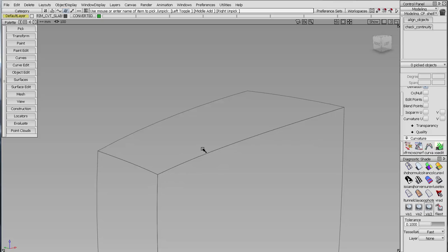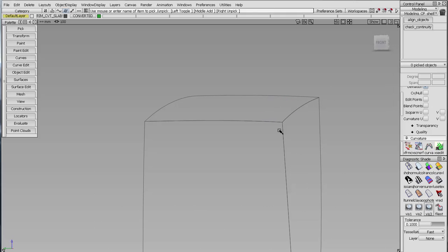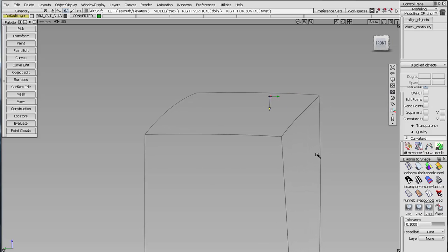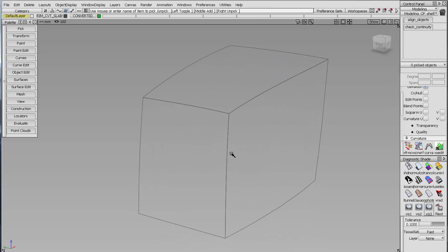And what is not a good intersection? Well, in this view, this intersection has compound or two directions of curvature, positive and then negative. As I roll this around to a more front view, you can still see here it's crowned this way, here it's crowned the opposite way, but somewhere in the middle it's an S. There's a flip-flop. So that's a difficult thing to judge and a difficult thing to modify using overbuilt slabs. This brings up why I like to use build to the intersection and then modify when necessary, as far as extensions and other things.